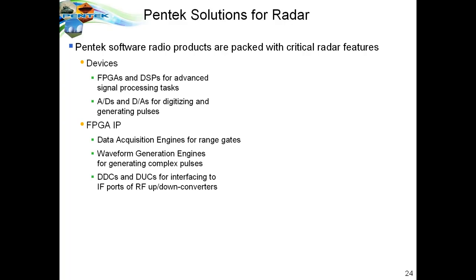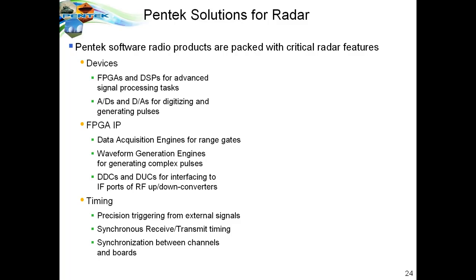Inside the FPGA, we include our waveform generation engines and our data acquisition engines, along with the link-list controllers. We include digital up converters and digital down converters for interfacing to IF or RF ports on your system. We spend a lot of effort in making sure that all of our products have synchronous operation across multiple channels and multiple boards. This is very important for phased array applications.